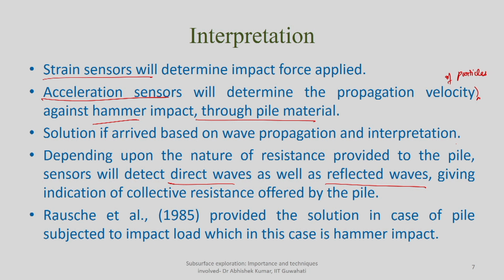So, depending upon whether the medium is offering some resistance, the reflection will be in which parameter, or whether the medium is not offering any resistance, then the reflection will be of what parameter. We are going to see that in the coming slide. Rossi in 1985 actually provided the solution in case of a pile subjected to hammer load. In this particular case the impact load is hammering at the top of the pile, and Rossi et al. provided the solution for this.